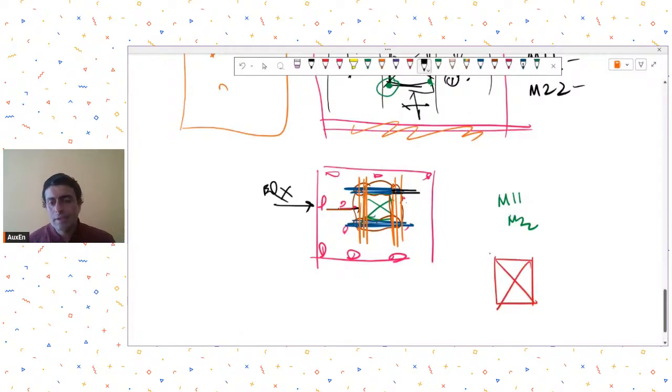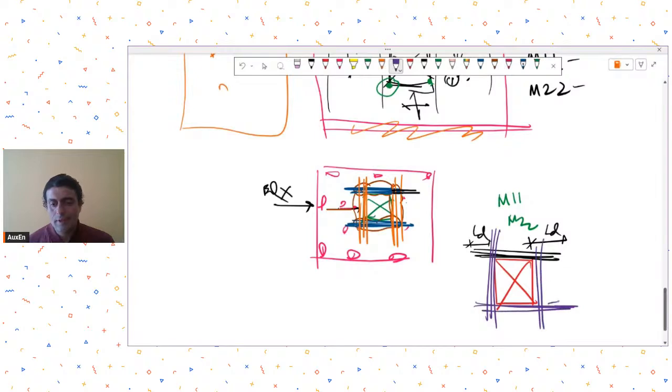That means, let's say whatever reinforcement you had worked out, you continue it till a distance so that adequate development length is provided. Okay, so take the reinforcement till LD distance. In some cases the code suggests you to take it till 1.25 times LD also. So in a few clauses in the American code, let's say, suggest you to take the reinforcement around the opening till 1.25 times LD also. So it depends, but the basic principle is that you need to have the reinforcement developed till LD at least